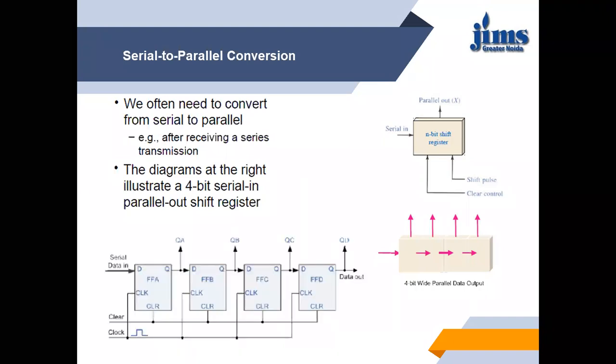So here is the connection. We have given a clear to all the flip-flops so that the initial data is 0. Clock is common to all flip-flops and the normal connections are there. But what we have done, instead of taking the output serially, is to take the output in parallel from each flip-flop.